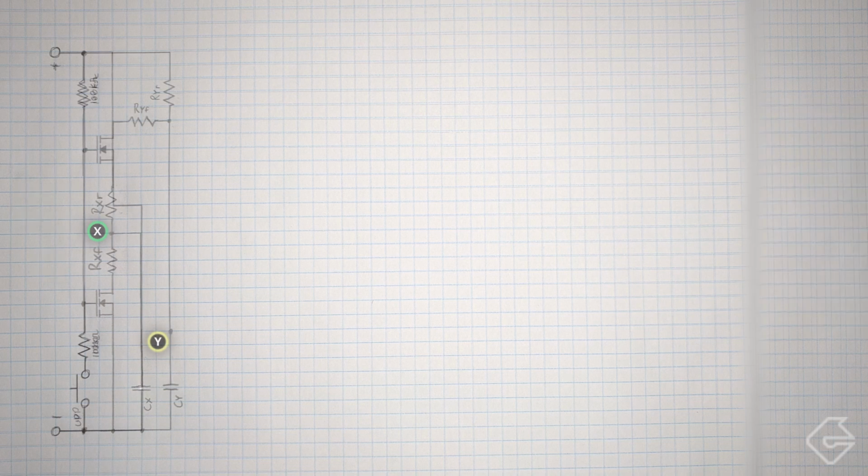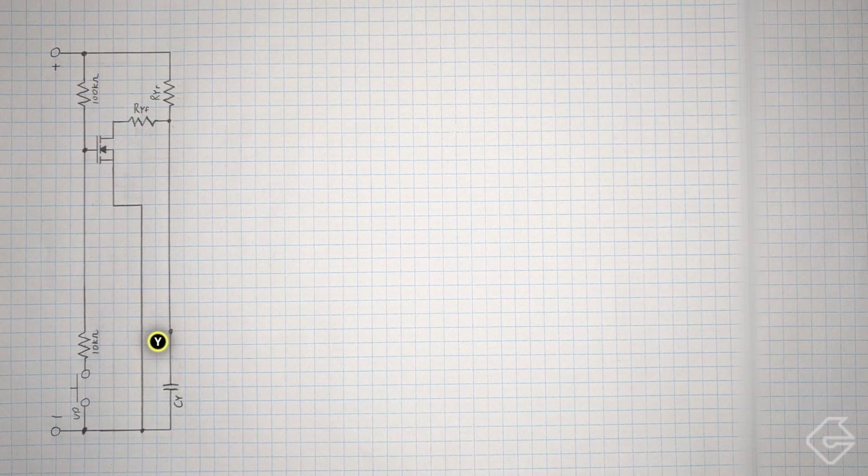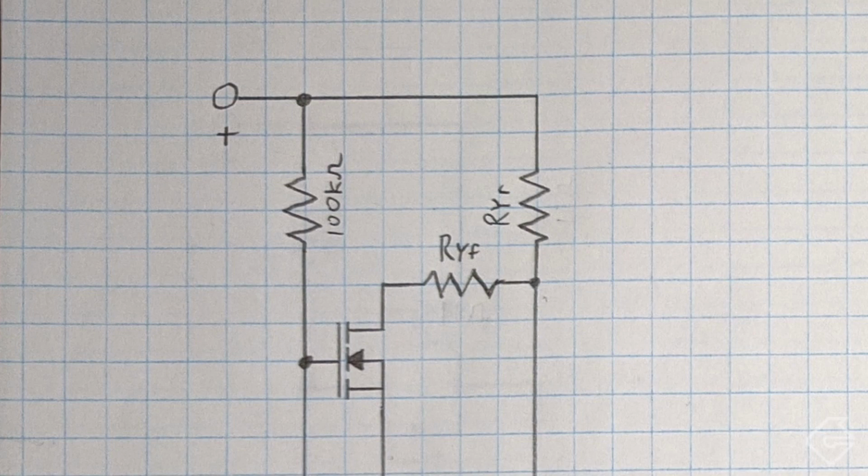Let's look at Y. So Y is being driven by the same switch. Don't forget, the same button is driving it, and I need to invert the signal. So if I try to do something like this, then I can invert that signal, but here's the problem. With position X, we needed a rise time that's long and a fall time that's short. With position Y, that is not the case at all. In fact, with position Y, the rise and the fall time are the same. Remember the sentence that we came up with, so the pair of sentences.